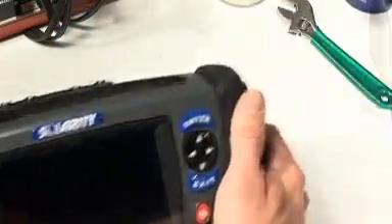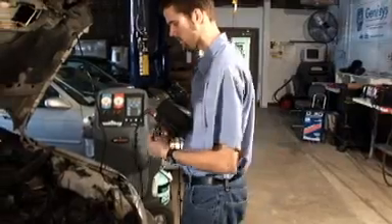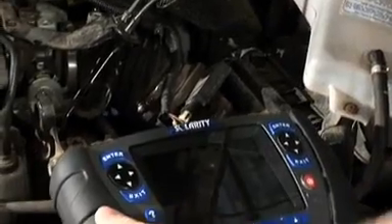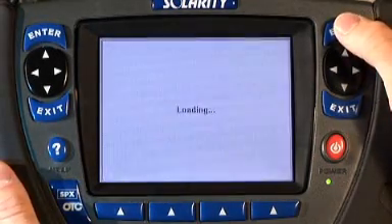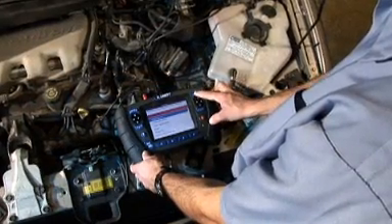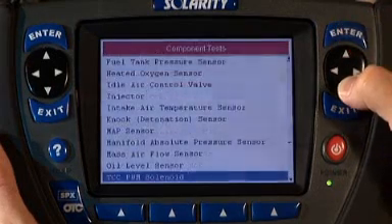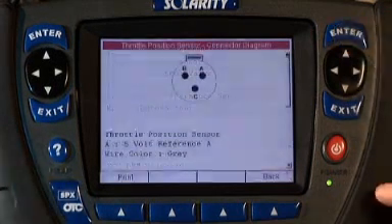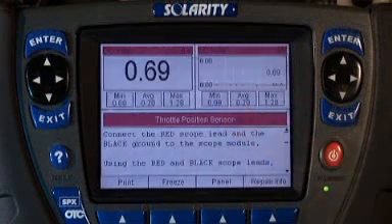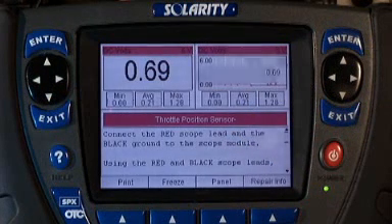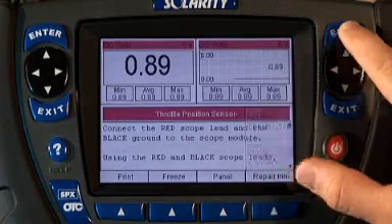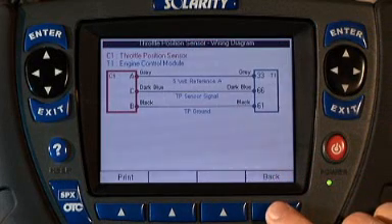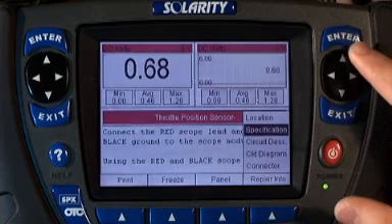At this point, he would use his OTC Solarity 4-channel scope with Infotech software. The technician enters the make, model, and year of the vehicle just as he did with the Genysis. The Solarity provides all the necessary information to properly connect the leads, run the test procedure, display the signal pattern properly, view connector and wiring diagrams, and compare test results to component specifications.